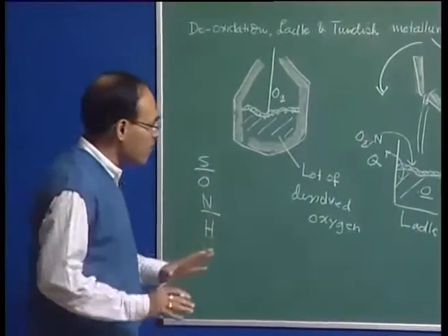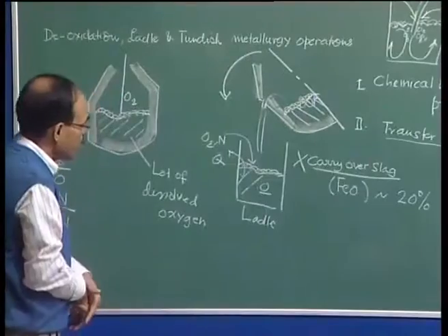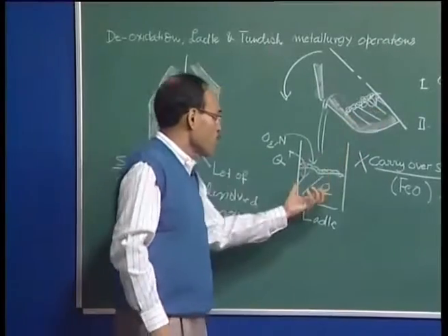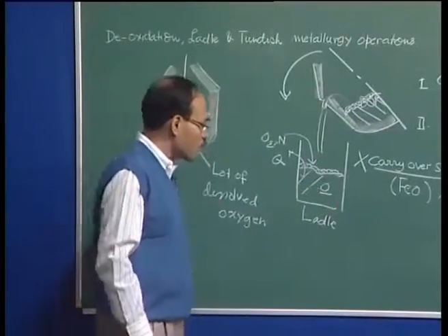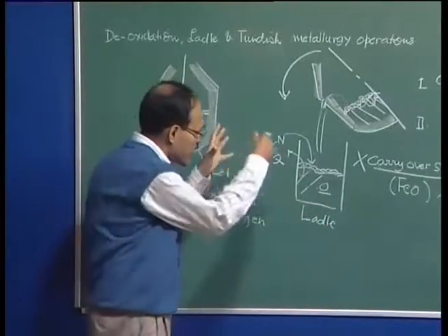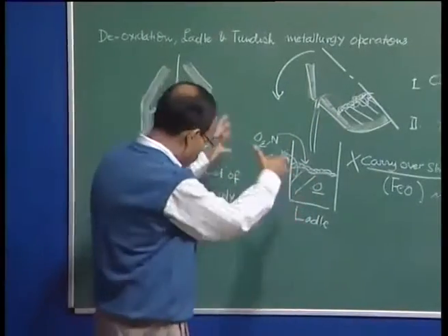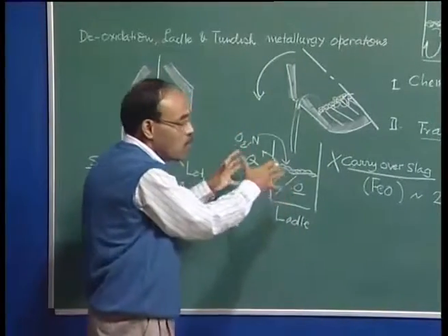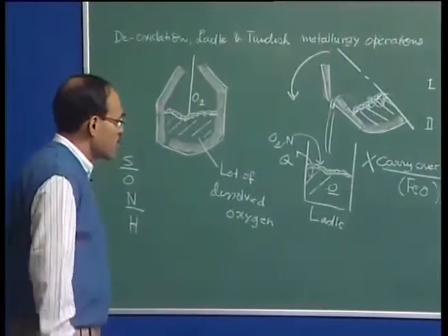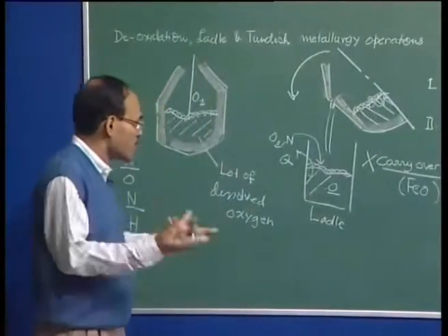We must understand here that the capacity of a ladle is identical to the capacity of a BOF or an electric arc furnace. So, if we are talking of 130 ton capacity, we are going to have 130 ton capacity for the ladle also. There are going to be innumerable ladles in the plants, and the ladles are typically recycled, because this ladle which is below the oxygen steel making furnace will be moved from the steel melt shop to the ladle metallurgy station, where we may carry out a host of treatments or a variety of processes, including tank degassing, ladle furnace to raise the temperature, composition adjustment, gas stirring, etc.